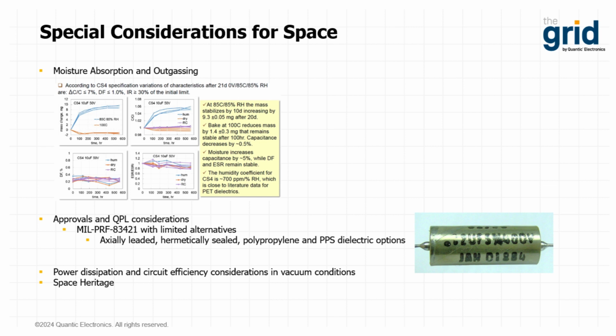One of the more interesting high reliability applications we're currently working on with the MLP is ion propulsion. So this is a very low power propulsion system for satellites and small space vehicles, basically to redirect their orbit. In this case, stacked ceramics were originally being considered for the same application, but they were having issues with piezo effects from the ion propulsion waveform, which was hammering those capacitors. They were not mechanically flexible and ended up cracking.